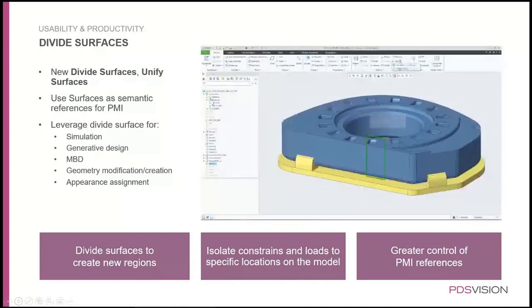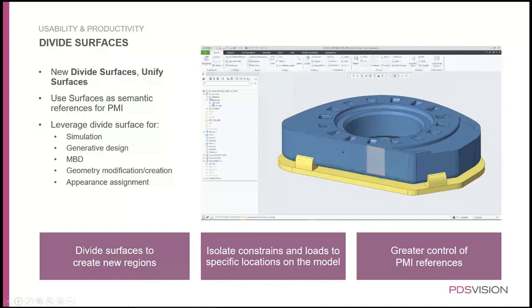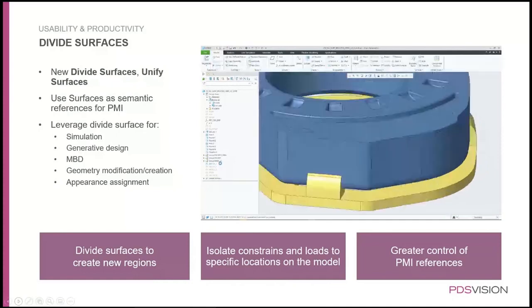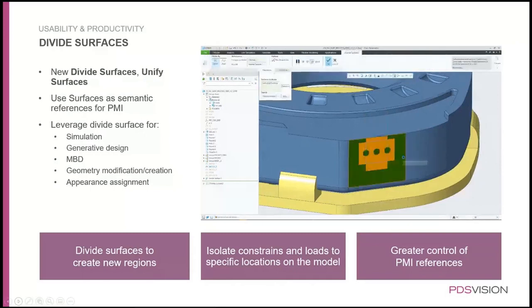In here, what you can see is the new functionality. You simply click the existing sketch or create one on the fly, and then click the surfaces to be split. Select the side which is the new feature, and as you can see, the color is now changing. If you have pre-made sketches, you can use existing functionalities like sketch regions to select which loops you want to keep, and then select the surfaces that you want to split.